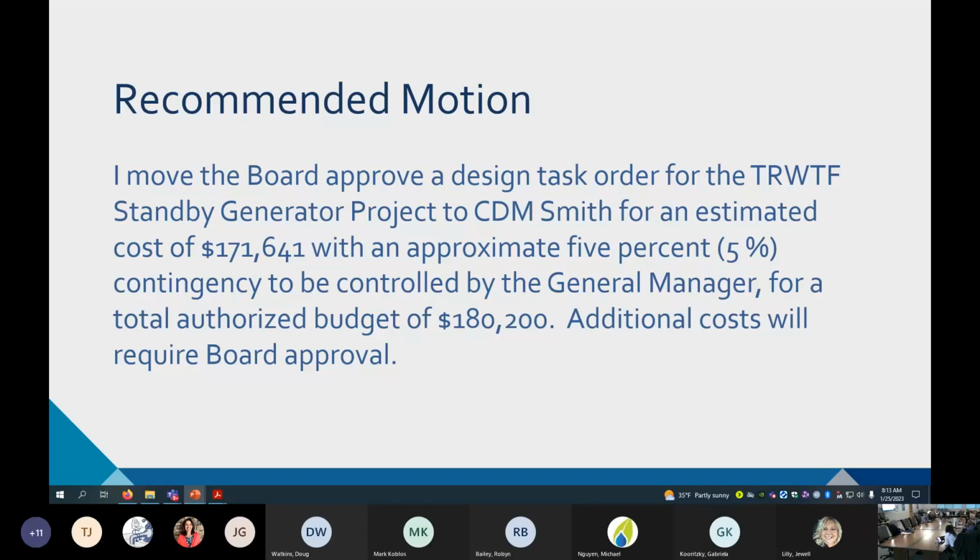The reason why I asked you that was to help me and others on the board understand here, that if you have paralleling systems on the generators, not all generators do, but if you have a paralleling system on the generator, that gives you a stronger backup.